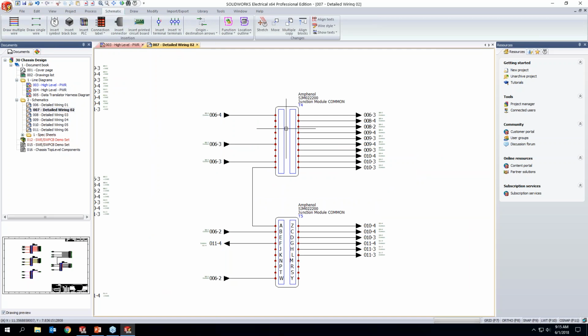let's say I have a 30-pin connector or a 50-pin connector, and that 50 pins, I don't know about you, but in most cases, I've never been able to actually get all 50 pins on one sheet. 2 pins on one sheet, 10 pins on another. Maybe I'm separating my power pins, 3 line, neutral, ground on one sheet, and all my comms on another page. Now, if I make that change, or if I have multiple symbols associated to that one